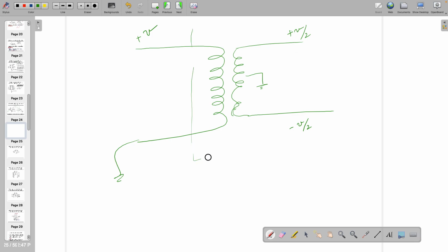By the way, this particular circuit, electrical people call it a transformer, but we don't call it a transformer. The very popular name is balun. RF engineers, communication or VLSI engineers, they are using this. They are making that actually. You have to make your own transformer or balun, which is going to give you the differential signal.